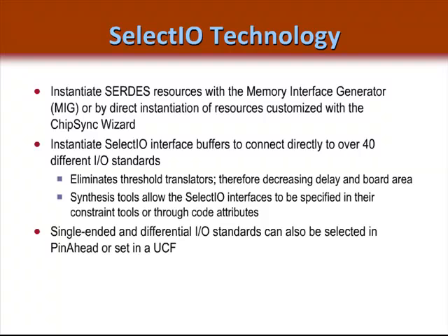If you're going to select an I/O standard, you can use the PinAhead pin assignment utility and add the appropriate assignment in your design's UCF file, or specify the standard with your synthesis tool, either through the synthesis tool's constraints tool or through an attribute in your HDL.